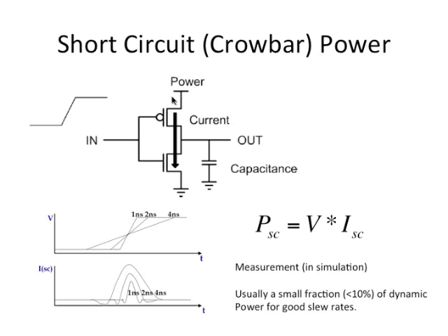So when you have this step, the capacitor current is just falling through the NMOS, but the supply is supplying current through the PMOS, right? So it's the PMOS which essentially determines the short circuit current. Now if my input step happens very fast, there is not much time for the output to have reduced, and I think that's what your friend was saying.